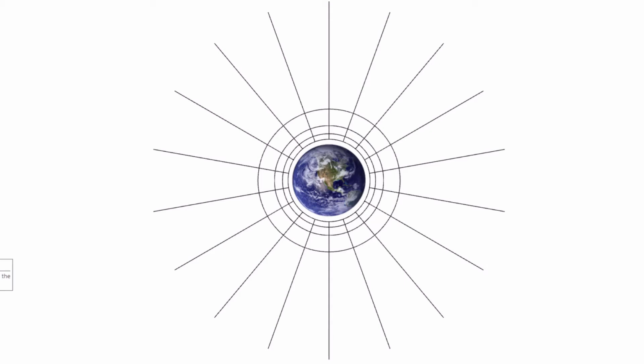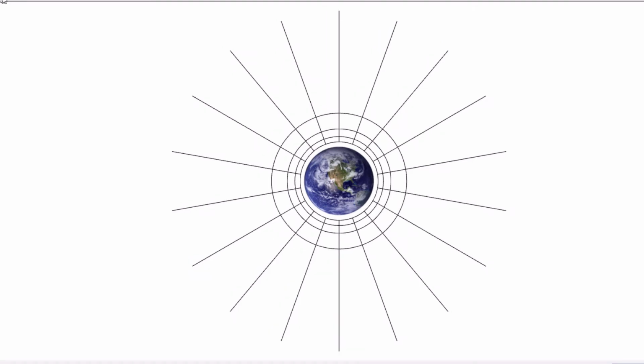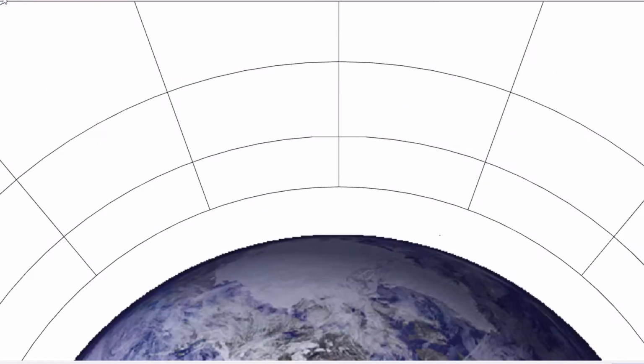Plumb and level references describe orientation with respect to the direction of gravity's force. Orientation which is exactly the same direction as gravity's force is said to be plumb. The orientation which is perpendicular to the direction of gravity's force is said to be level. Other terms used to describe orientations that are perpendicular to each other include square, right angle, and 90 degrees.